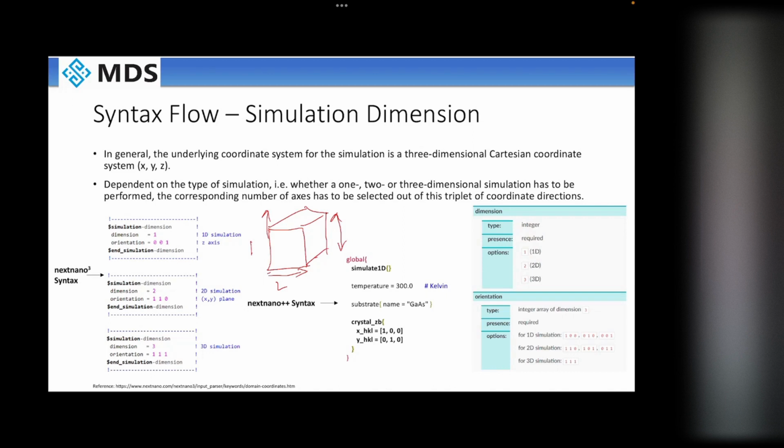If we do a 3D simulation of this device, making a contact on the top or maybe at the bottom, it doesn't make any sense, because if you take a 3D dimension, then the mesh points will be more and the computation will take more time.